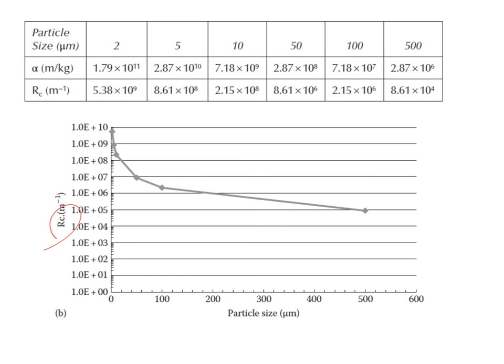By assuming that this porosity is 0.5, we can remove these additional terms here. So what we can confirm is that if we increase the particle size, the cake resistance decreases significantly, assuming that the cake mass is constant.